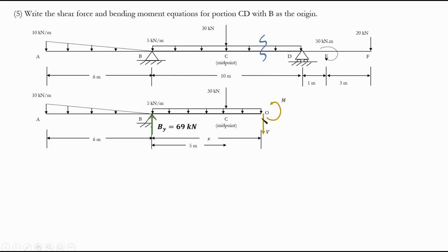Shear is, in this case, as we know conventionally, going in the clockwise direction. Moment is in the direction of compression at the top, right? And again, you don't have to remember that because I'm going to do both of them. So just remember these. When you take the left side, your shear and moment are going to look like this, in terms of direction.